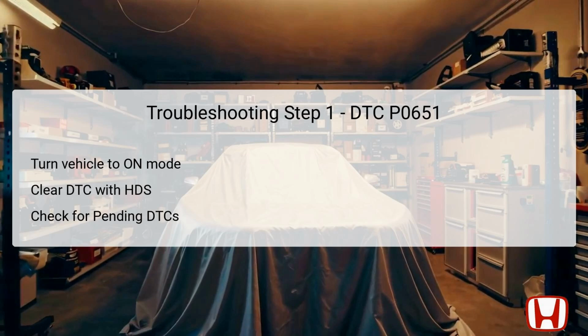Conversely, if the DTC does not reappear, it suggests that the issue may have been intermittent, and it might be worthwhile to inspect for any loose connections or poor terminations at the PCM and associated sensors.